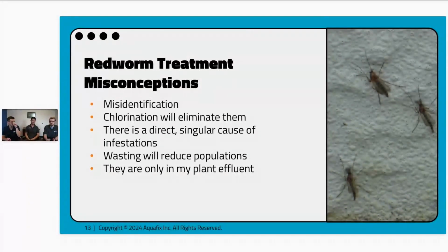The biggest sign, as we kind of talked about, is losing mixed liquor numbers for no apparent reason, which could be an indication of what's going on. And obviously treatment then has to take place with losing mixed liquor from the worms. And a lot of times you see them in your samples, when you take a 30-minute sample, you see them. Just because you don't necessarily see them anywhere else, they're in there. That is the best time to take action before they get to the point, like Dalton says, where they're starting to impact your mixed liquor, because then you're infested and then you're in trouble.